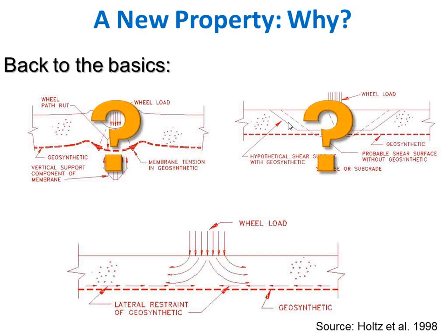With the traffic loading, this base will try to move laterally, distend laterally. The base will lose confinement. And consequently, the presence of the reinforcement minimizes this tendency of the base to distend laterally.